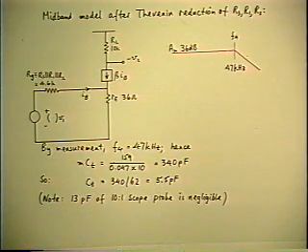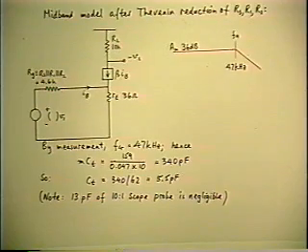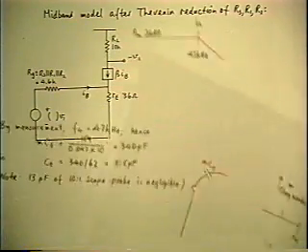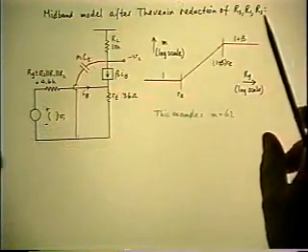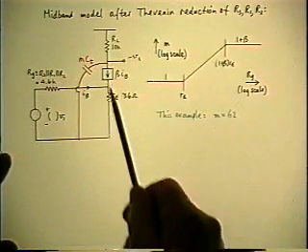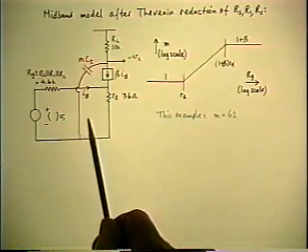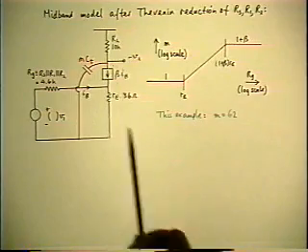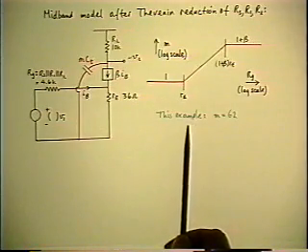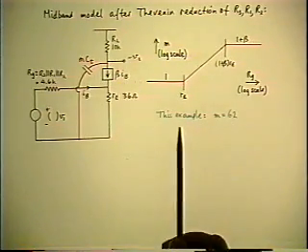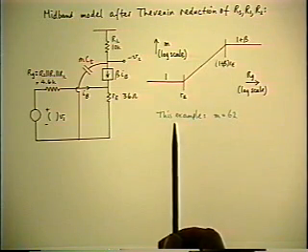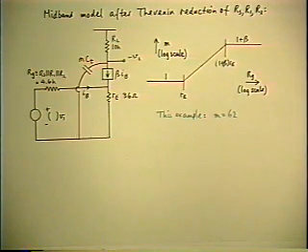So when I make this substitution, I have to multiply the value of that capacitance by the M in order to get the right answer for the bandwidth. So it's an equivalent circuit in that sense. But it's hazardous to do this.